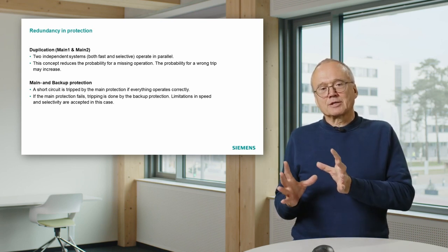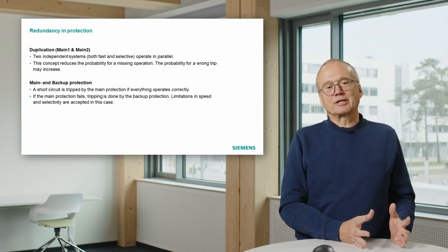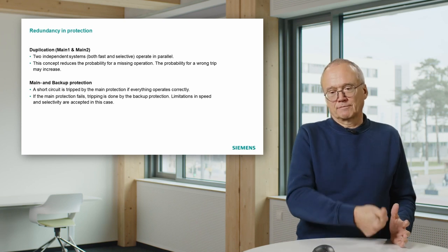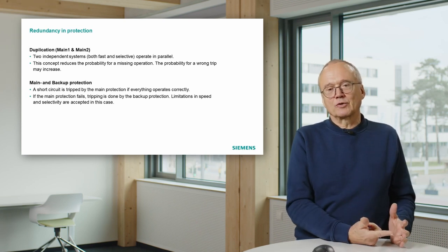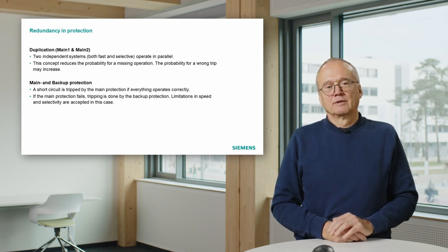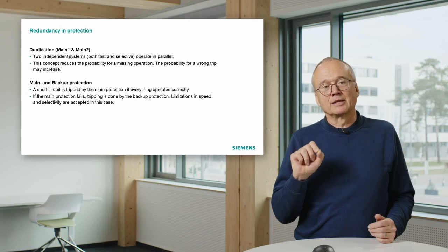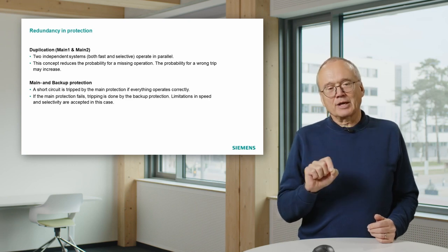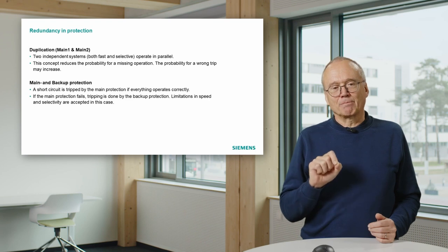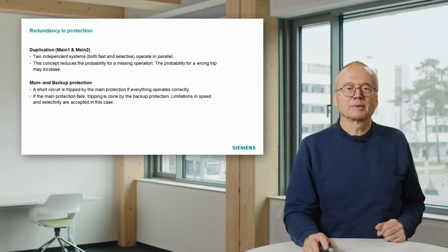Economic constraints bring you in a situation that you accept additional risk. Well, you have reduced selectivity, longer tripping times to save some money. But it's state of the art to do that. And an important rule behind that, in all cases, you must think about which device does the backup in case of a missing operation. That's always the idea behind it.